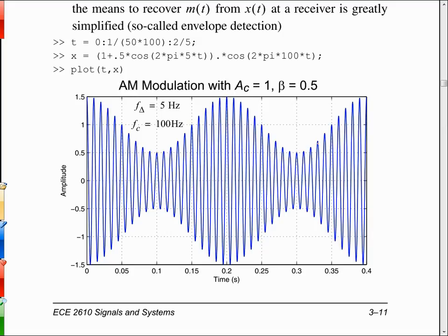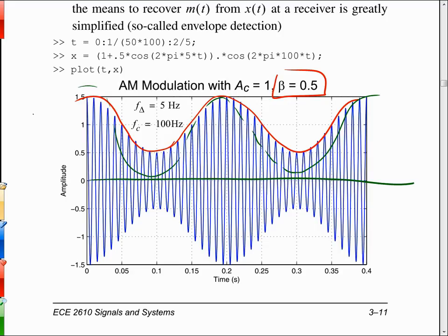So when we see the modulation index here, beta is equal to 1/2, we can see that the modulation is just causing this envelope fluctuation. So the carrier amplitude, rather than being steady, when we multiply it times 1 plus beta times m of t, it's fluctuating up and down like this. And as long as we keep it less than 100%, we'll never cross 0 here. If we were to drive it right up to 100%, we'd be coming down something like that. But as long as we keep it below 100%, there's no touching zero right in there.